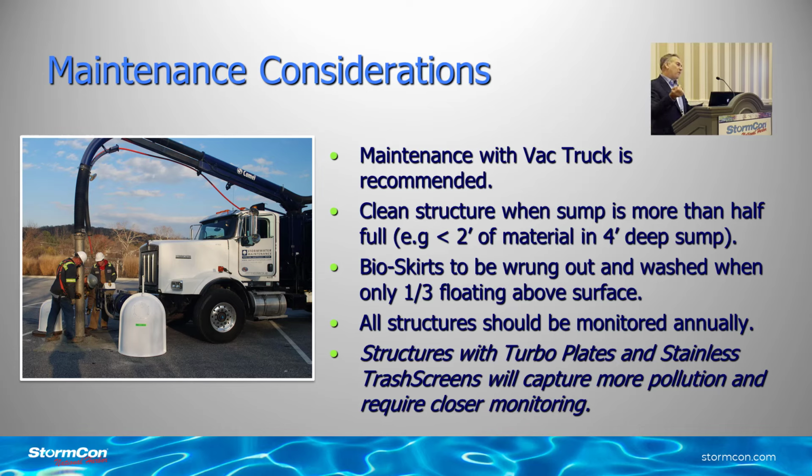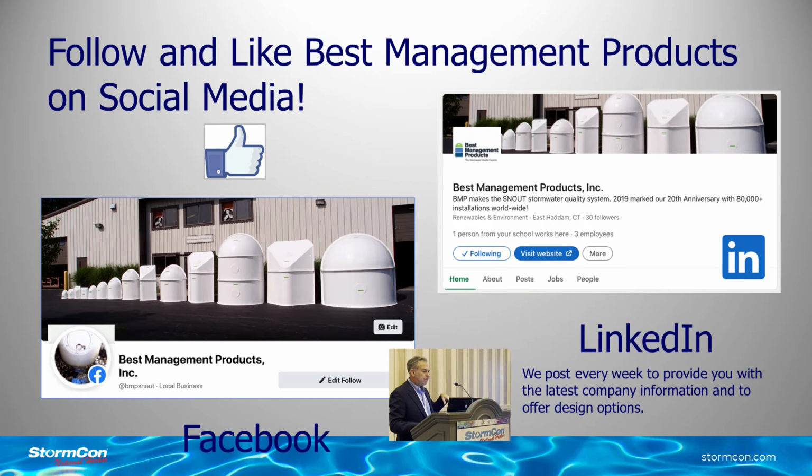So, you have a 4-foot sump and you think, oh, I have all this storage volume. Well, you have that volume, and it has a capacitive effect to allow things to settle out. But what's going to happen is you are decreasing your efficiency because at some point you're going to hit a steady state. So it's important. That's why I put clean it out when there's 2 feet of material or 4-foot deep stuff. You're going to find that structures with turbo plates are obviously going to collect a lot more sediment faster.